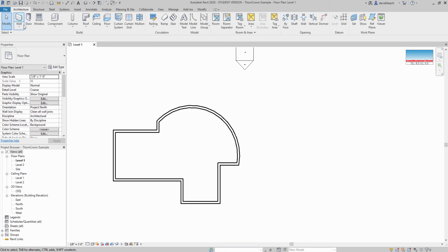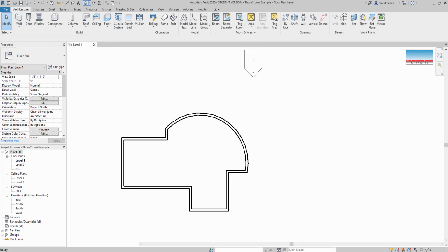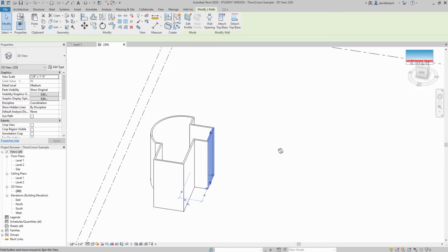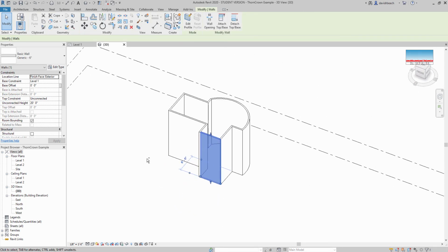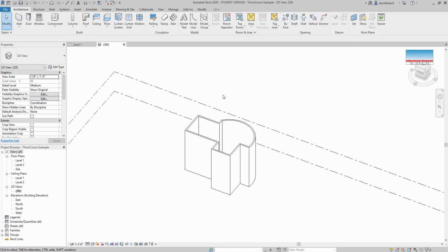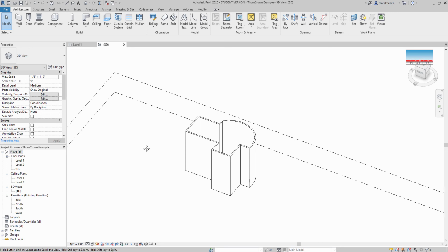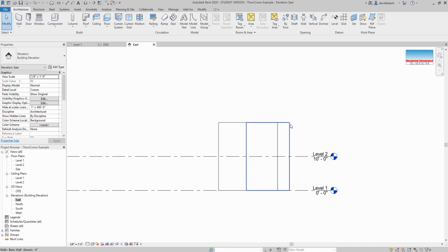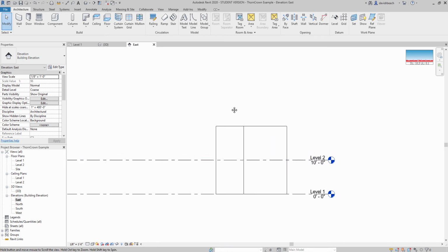Next, as I'm building these walls, it is putting them together entirely in 3D. So I have all of this information coming together. If you remember, these walls are 20 feet tall. That's how we drew them. And they are unconnected. So in other words, there's nothing that's attaching them to a specific point. As you improve in your Revit skills, one of the things that you're going to find that you want to do is actually begin attaching these walls to a level.